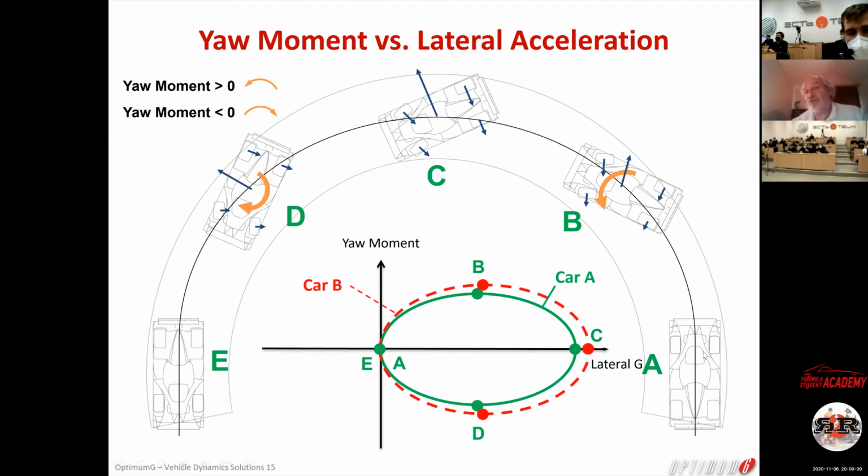Okay, so you start to understand that, okay, quick summary already after 15 slides. On a race car, you want maximum grip. How do you get maximum grip? Give me better tire, give me better downforce, give me the right camber, the right slip angle, the right temperature, the right pressure. That's why you need to understand your tires. That's the number one thing to do.